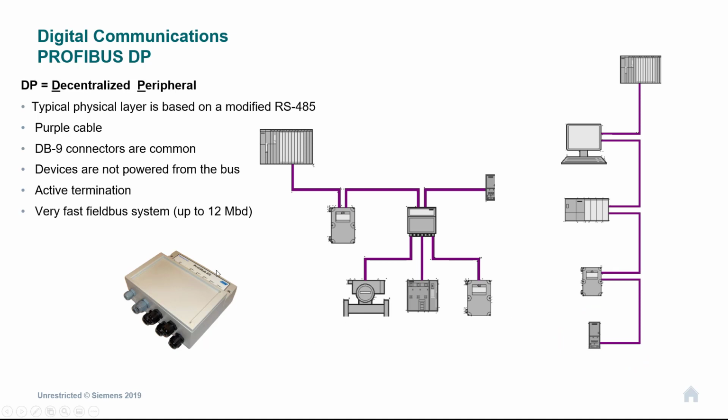So there are devices on the network that can act as splitters. What that allows us to have is a Profibus DP spur to go off to the instrument separately. So if I lose this instrument or I break this cable, I only lose this connection. And nine times out of 10, the cable damage is going to happen in the field. So this would make more sense.